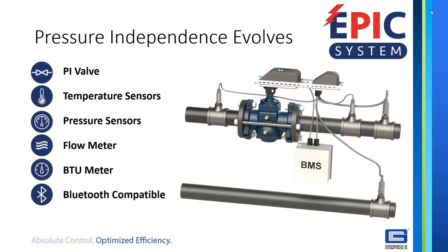I'm going to move now to the next category, which is using the pressure independent valve in our EPIC system. And so historically, we said you want to control your delta T by controlling the flow. And we talked about that last week and the week before so much that you're probably all tired of it. So we know that controlling the delta T is very important.